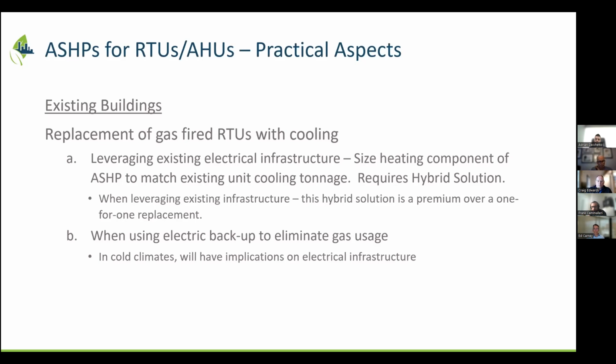So the compromise is, the lowest cost is just a straight replacement, and work with the wire size that you have. You might get lucky. Motor efficiencies have gone up. So in some cases, we can go to slightly bigger tonnages without changing the wire size. So you might get lucky that way.